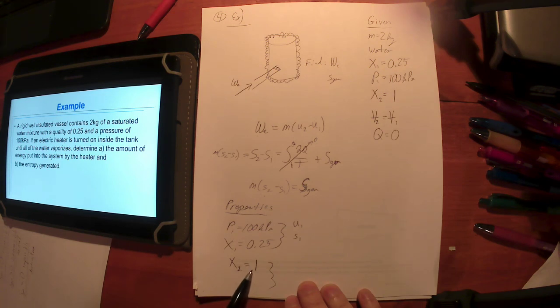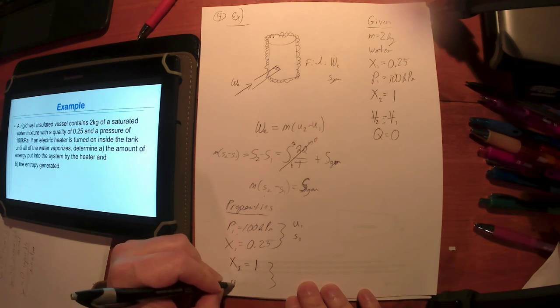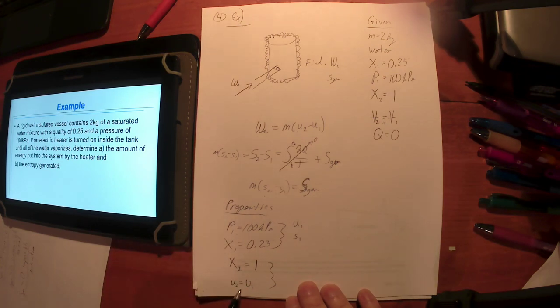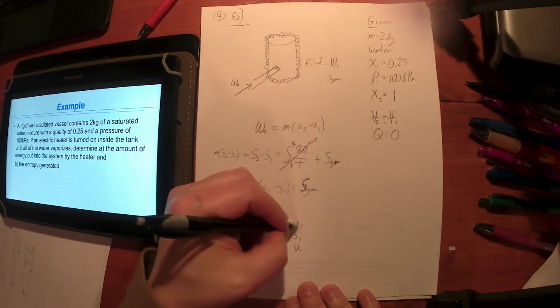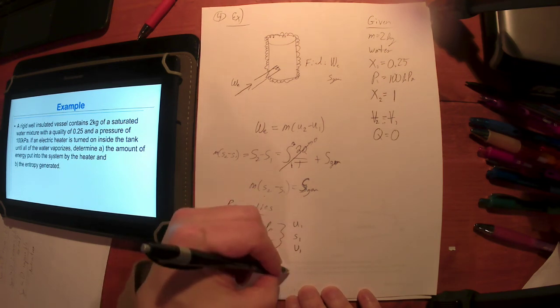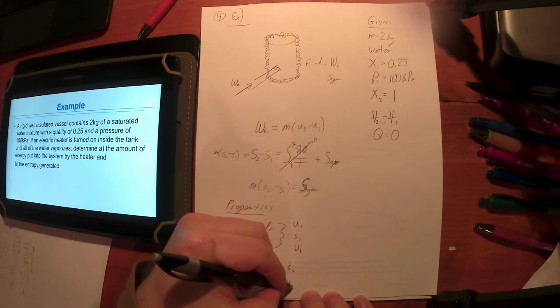The common thing is, is there anything constant? Not pressure. Nothing says the pressure is constant. In fact, closed system, that's not a good gamble. What else is constant? Volume. So if total volume is the same and mass is the same, that ratio of total volume to mass, the specific volume, is the same. So if I can get these properties, I can also get the specific volume in state 1. These two properties will be enough to get me properties at state 2.